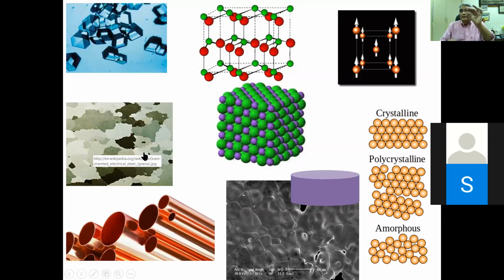You see a thick layer of iron oxide forming on it, right? That's why these are all chrome plated. Your bicycle handle is also basically made of iron, stainless steel, but it is further chrome plated because chromium doesn't get oxidized easily, right? So how beautiful it is, so you don't want grain boundaries basically, right?